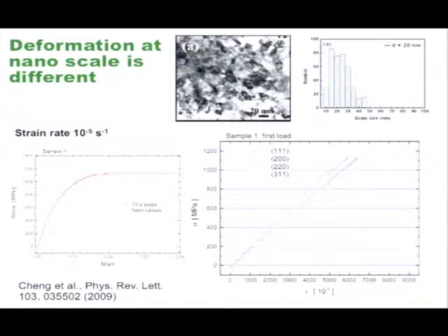But to my knowledge, no one was actually able to pin it down. You look at the different simulations from MD: grain boundary sliding, partial dislocation emission, and so on. But we have to be careful, though. These MD simulations are simulated on a different time scale, 10 to the minus 9, 7, whatever. So my challenge for them is, we measure these things. Please come up with a calculation that you can simulate, or calculate, and let's compare.